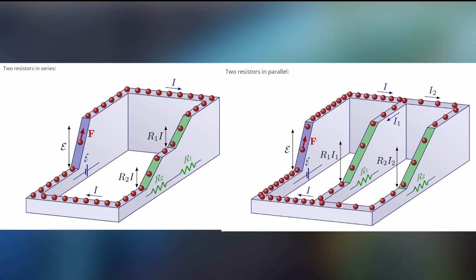However, the advantage of a parallel circuit is that if one component is removed or is damaged, then the entire circuit does not stop working. Only that component will stop working. So that's why in household circuits, components are wired up in parallel rather than in series. Because if you had every single power point in your house wired up in series, that would be really annoying, because it would mean you would have to have something plugged into every power socket and turned on, therefore drawing a current, in order to have any of them work, which would just be ridiculously inconvenient. So in practice, they're wired up in parallel, so that you can turn them each on and off individually.